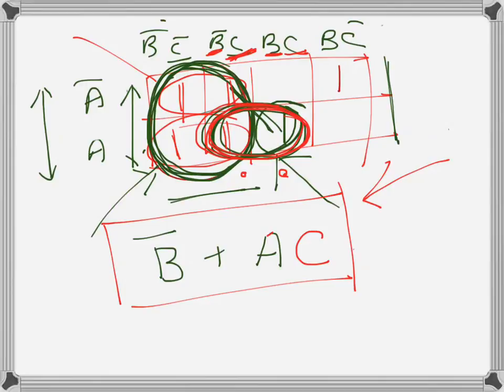And as we saw, there is an overlap here. That's fine. There is no problem overlapping, but we don't take any one if we don't need it. Like this one, I drew a 1 there, but I am assuming that there is no 1 there. But if there was a 1 there too, I would have to group it, but I wouldn't group it alone. This one would go with this one. That's the biggest group I can get, because this one is not adjacent; it is diagonal.